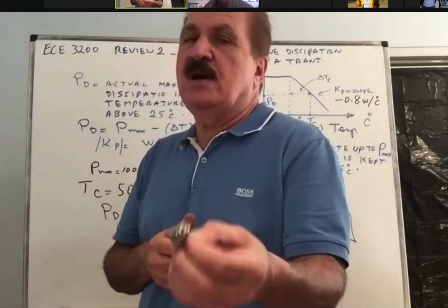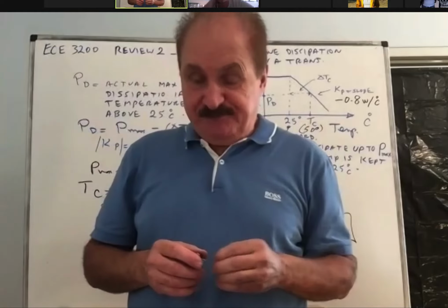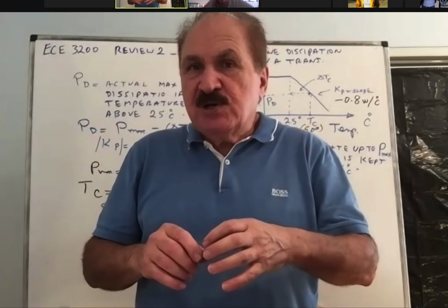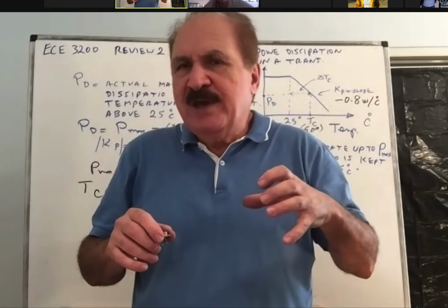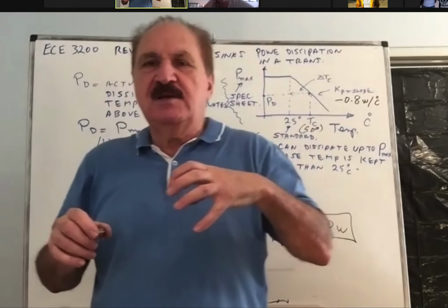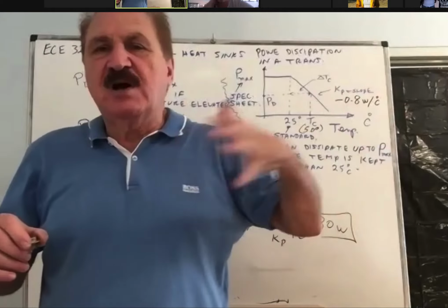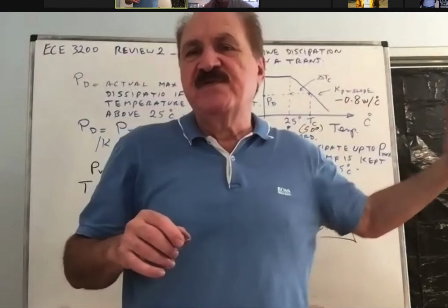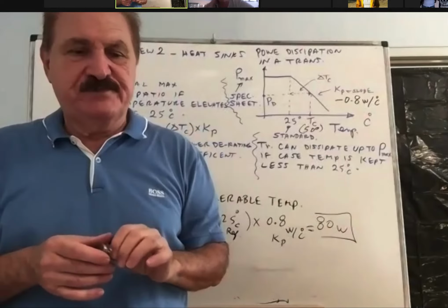the case temperature at that rating, I'm 100% sure, will be way, way higher. It won't be able to sustain, because as you put that much power in it, the temperature will keep shooting up. It will go quickly to 50 in 2 seconds, and then in another 2 seconds, it will go to 100 Celsius, 150, 200, 250, 300. By then, it will fail.